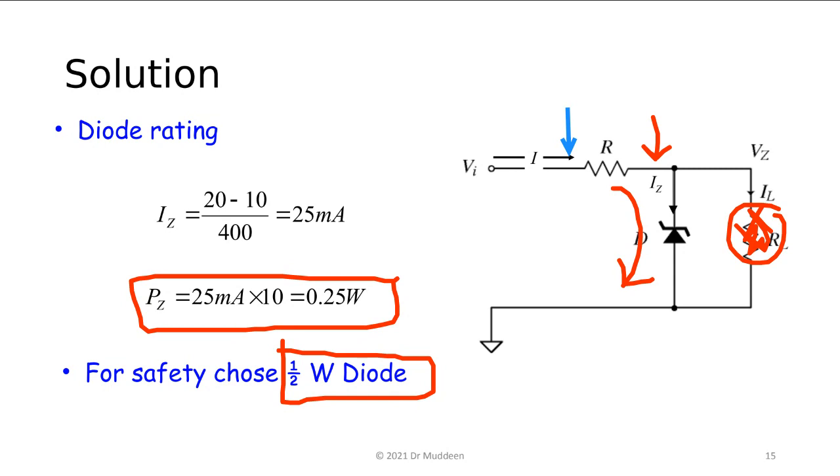You go down to Shams Electronics up in the north here, and you tell them, now I want a 10 volt half watt Zener diode, and I want a 400 ohm, well, again, the same sort of thing, a 400 ohm half watt resistor, because I'm building an unregulated power supply. Fair enough?